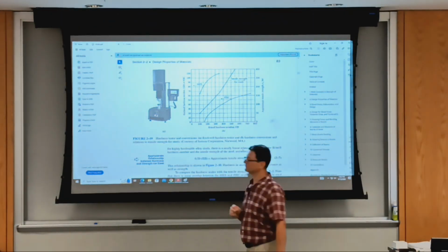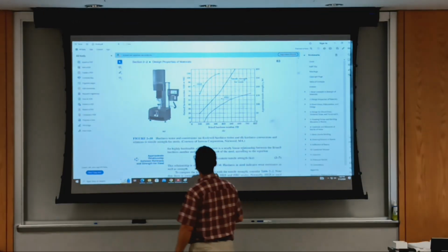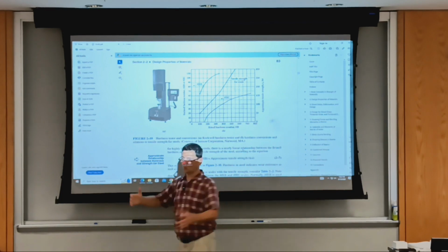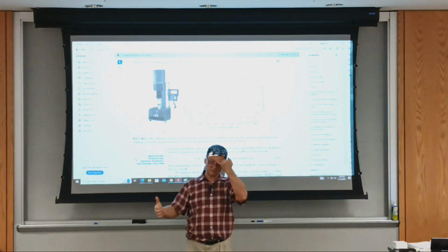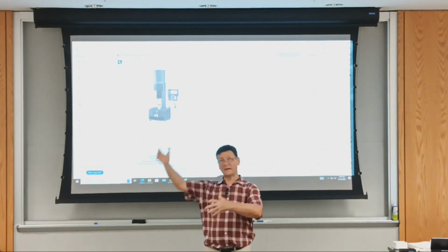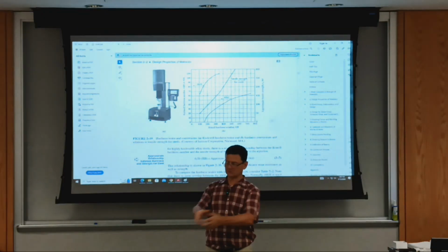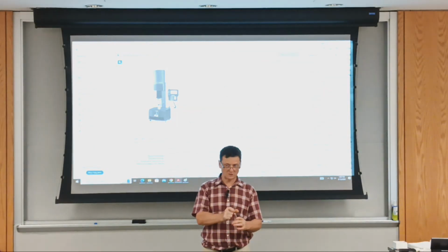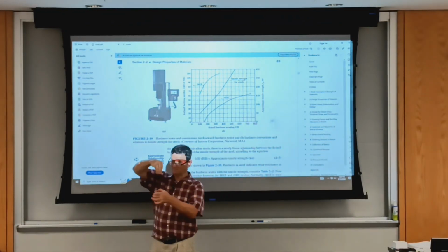The ball can be made of carbides, which is stronger than steel, and again it was easy to do. The load is standard, 3,000 kilogram force or 500 kilogram force. You just have a big weight, and you lift it and let it down onto the surface. You take the specimen out, you measure the diameter. But nowadays, the equipment has a means to measure the amount of indentation.